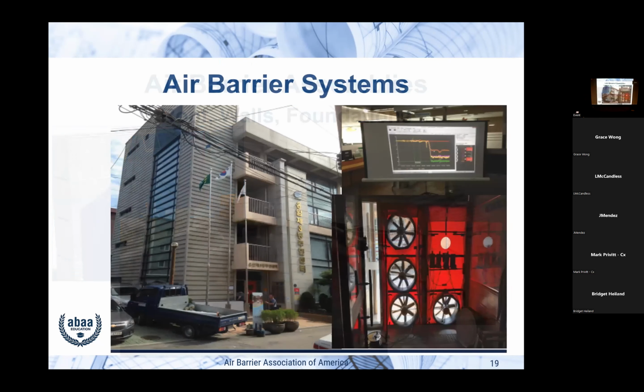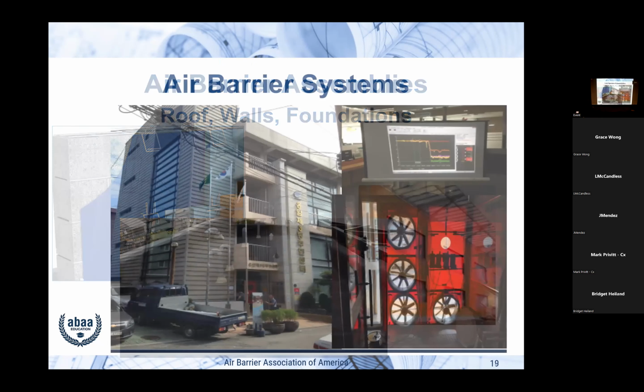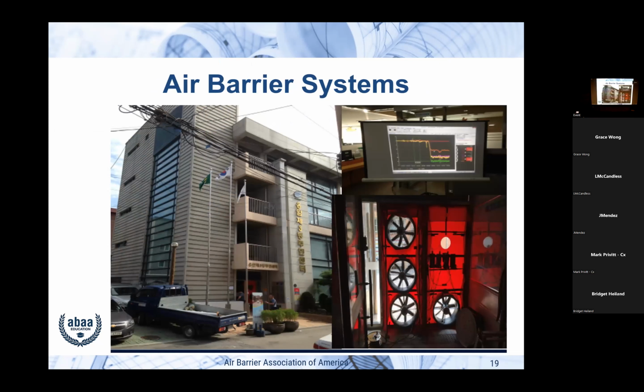And we have the same issue, just going back here, like we talked about penetrations in the walls and windows and so on. Same thing with your roof. And so the two ASTM test methods for testing roof assemblies have those type of penetrations in the roof before they do the testing. And so how much air leakage you have when it's not just a single piece of material going across there. So that's an important test that's out there too. And then you have the whole building test.